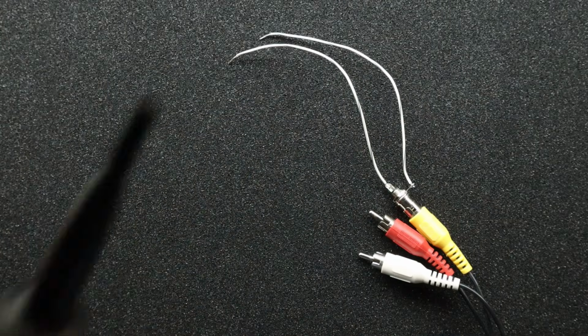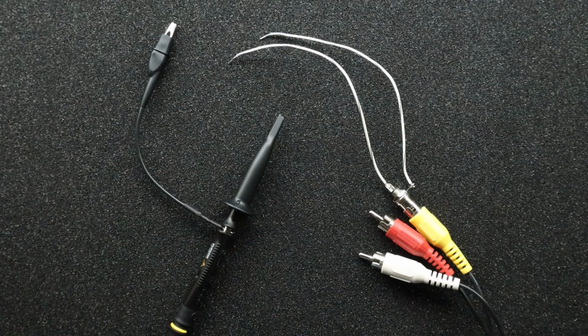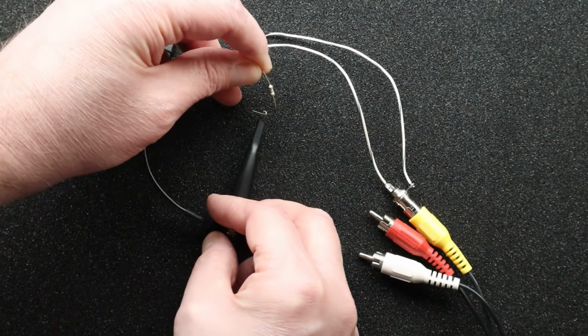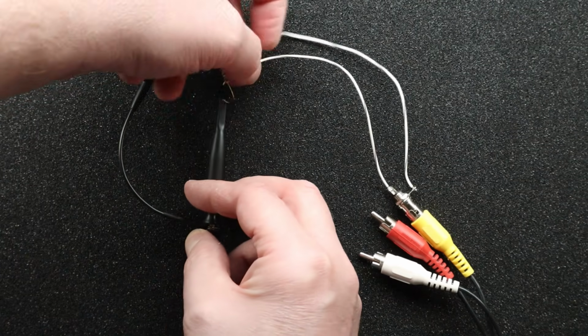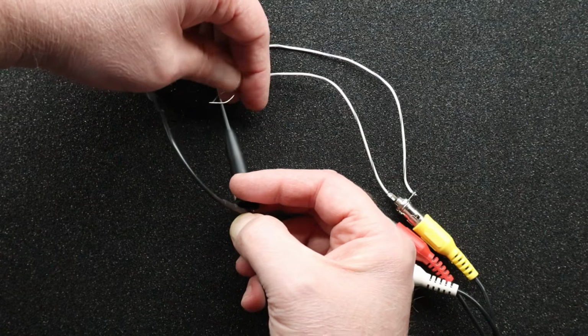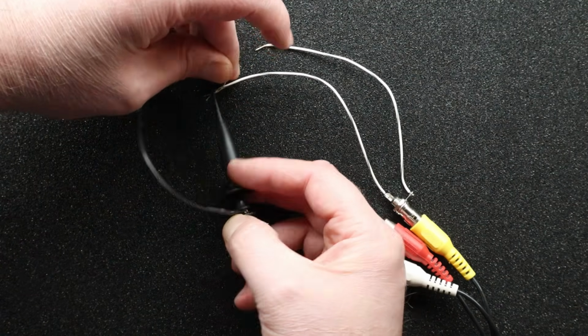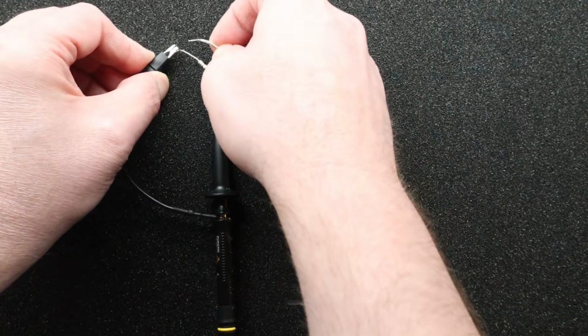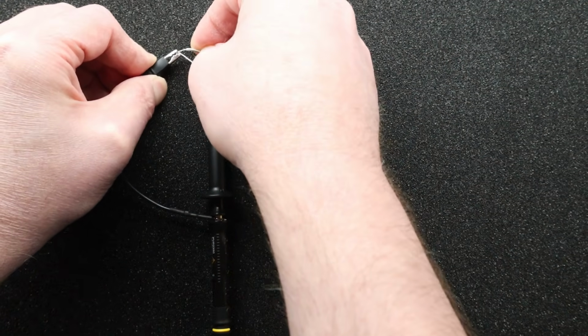Well, if we don't have internal impedance, then we need external impedance. We can actually use one of these standard scope probes if we place the impedance at the point where we probe it. You may have seen me do this in some past videos. I'll just place a 75 ohm resistor here when I connect up the scope probe. And make sure you're connecting the scope probe ground to the right place. The outer conductor on the RCA connector should be ground, and the inner conductor should be the signal. But it's your responsibility to make sure your connections are correct.